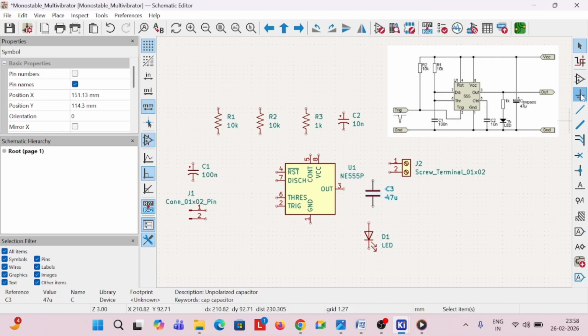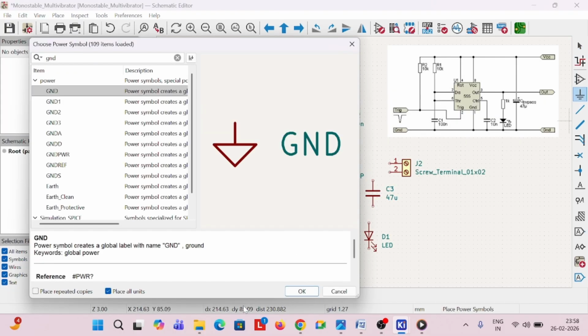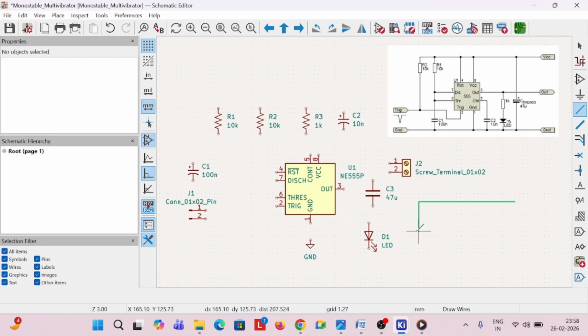So this ground, select ground. Let me connect this ground to this pin. If we press W, the wire will be selected. Escape that, just click on this, press W, then draw to this point. Now it is connected. Similarly, the LED, then to this LED. This pin is